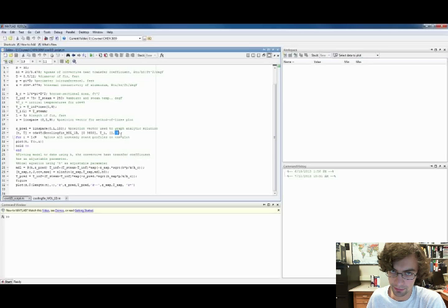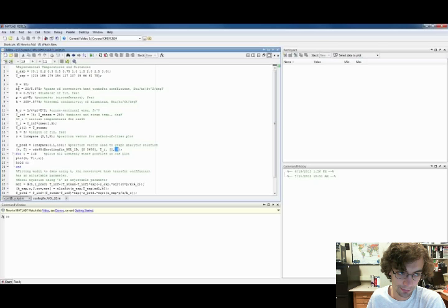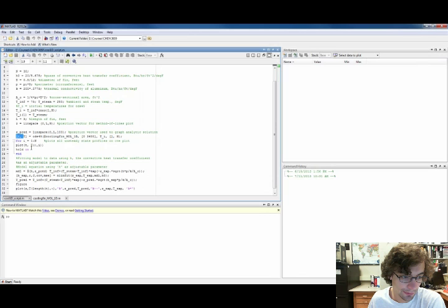I don't have any options here, so I just have empty brackets. You have to put those if you don't have any options, and specify things after that. The thing I specify after it is n, the number of nodes that I showed you before, and I specify that further up here. I just give it 30 because I assume the fin is 3 feet long, and so it goes in increments of 0.1 feet.